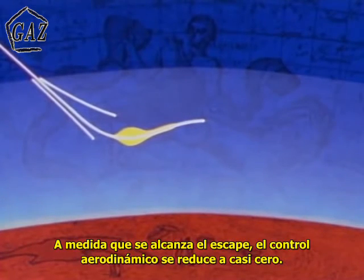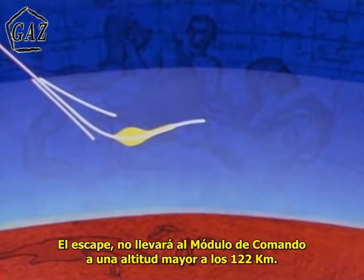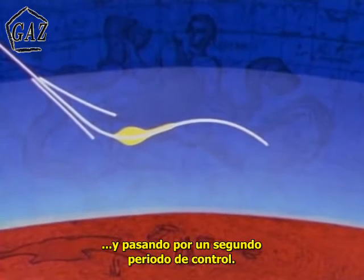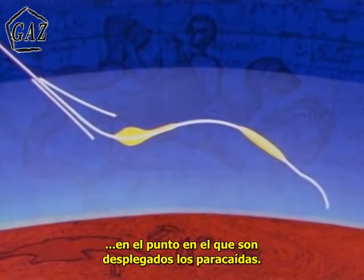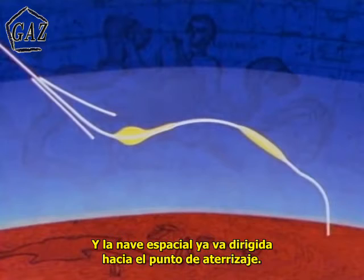As the skip is approached, aerodynamic control is reduced to practically zero. During the skip, the crew will be experiencing weightlessness. The skip will not take the command module beyond the 400,000-foot level. It will then descend, starting its second entry, and go on to the second control period. The entry phase is terminated at the 23,500-foot level, at which point the drogue parachutes are deployed, and the spacecraft is committed to its landing point.